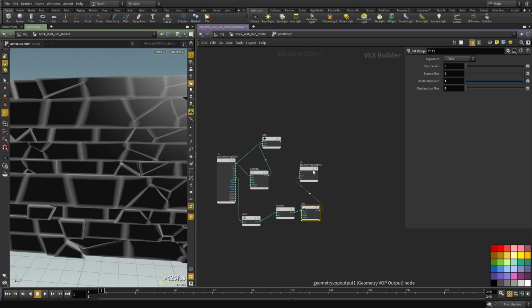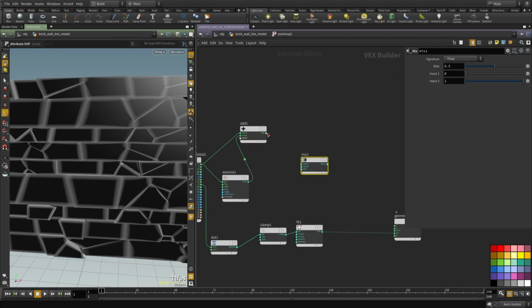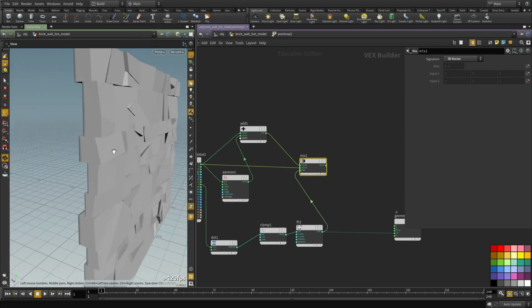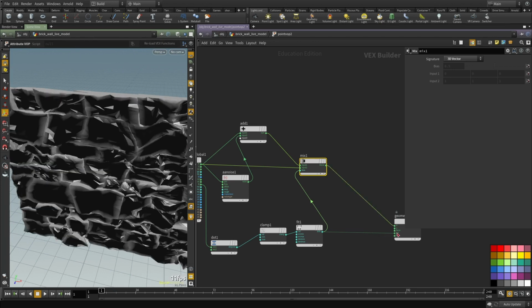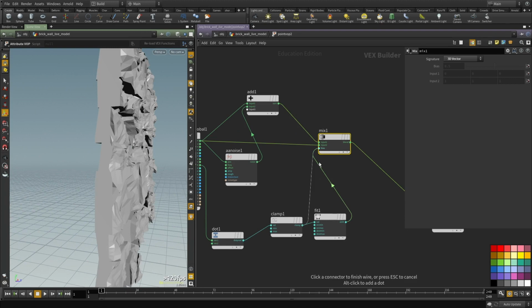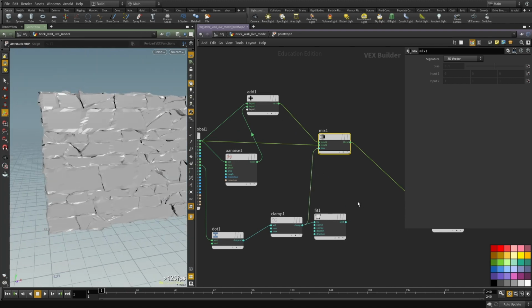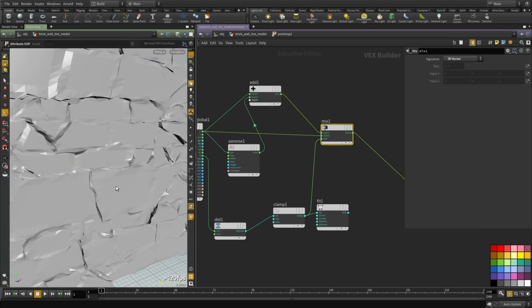So what we need to do is mix the modified position with the original position using this mask, so it only applies the modified points to where we have white values. So let's add this. And now it's doing the inverse, so let's connect this guy. Cool, I don't need the fit. And you can see now we're modifying everything except the front faces.